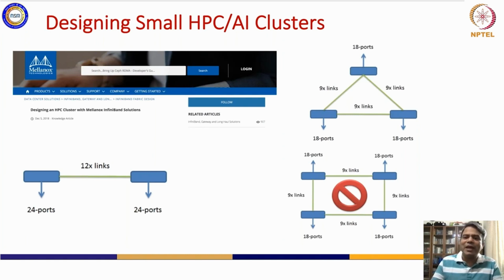It is actually a big device which contains multiple ASICs inside, and they are connected to each other in a certain way. For a single ASIC, there is a limit to how big an ASIC you can make. One of the simplest limits is the die size. You take a large wafer, and to get a good amount of yield, you will have a certain size of die on it. A certain size of die will be able to service only a certain number of ports, because finally you need to take electrical signals out of that die.